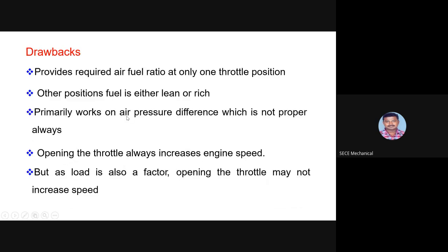And there are some drawbacks. It provides the required air-fuel ratio at only one throttle position, and in other positions the fuel mixture is either lean or rich, and it primarily works on air pressure difference, which is not always proper. And opening the throttle always increases engine speed, but as load is also a factor, opening the throttle may not increase the speed.